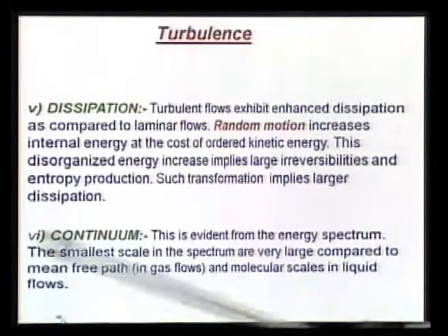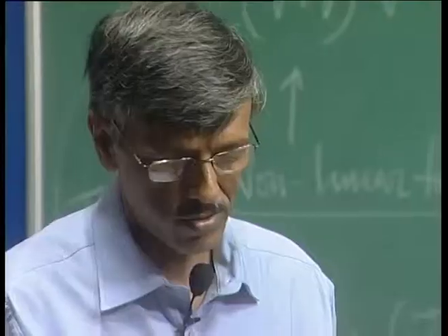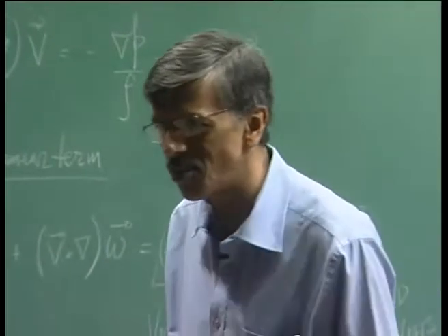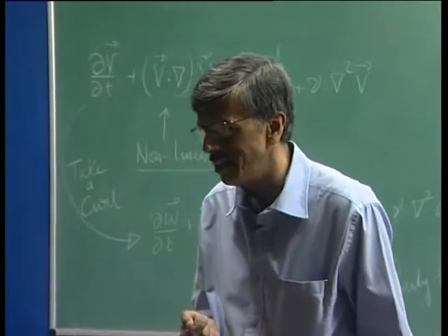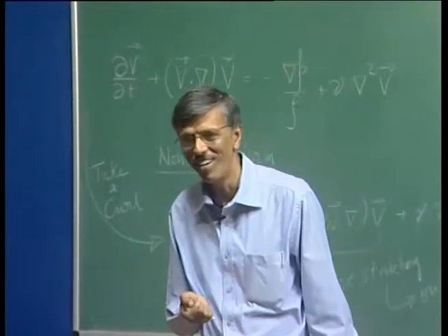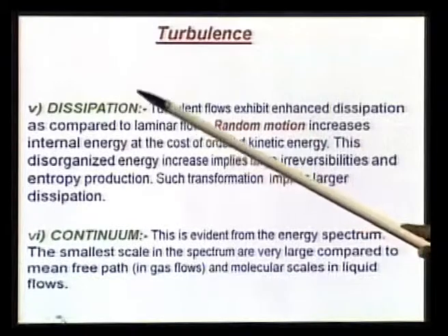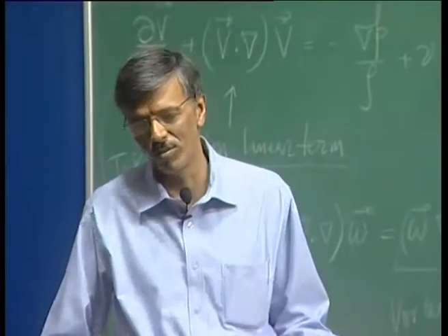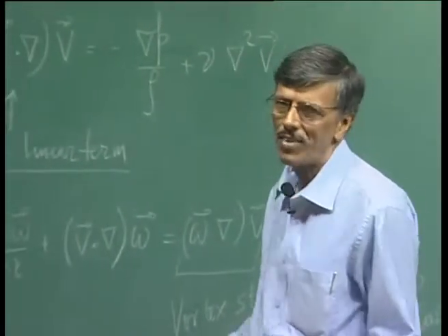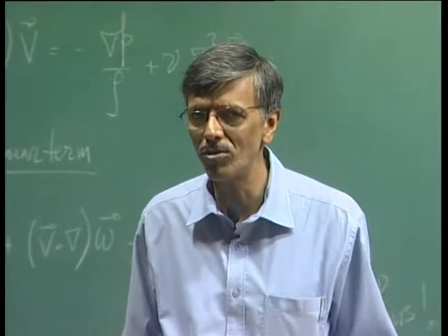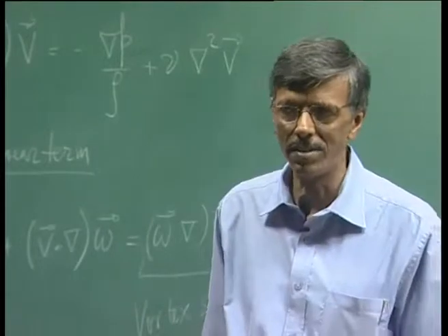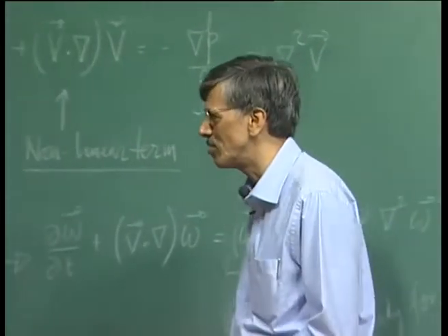The turbulent flows are more dissipative. You ask an airline operator, they will complain till their face turns blue that they spend all the money because flow is turbulent. They would love to have laminar flow. That is because we have very high dissipation in turbulent flows. Okay? We have very high dissipation, and that is not very unusual for us to understand. We already have talked about diffusivity. If I have larger diffusivity, I will have larger dissipation. So that's okay.